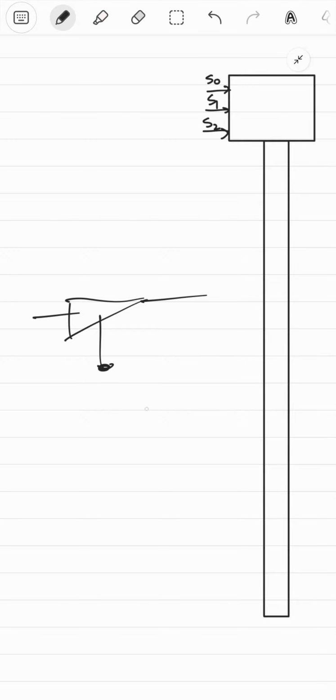You have an enable port, and whenever the enable port is off, we call it a Z, that is a high impedance state, as in there's nothing, no current, no voltage, nothing connected to this wire. You can imagine as if the wire is just hanging in the air, as if the wire is non-existent, you have removed it from the circuit. That's a high impedance state. Anyway, we won't be using that in proper professional circuits.